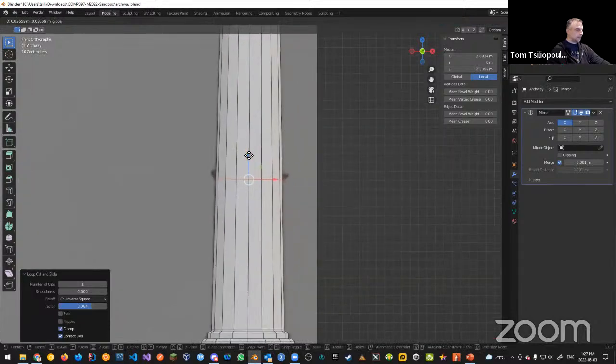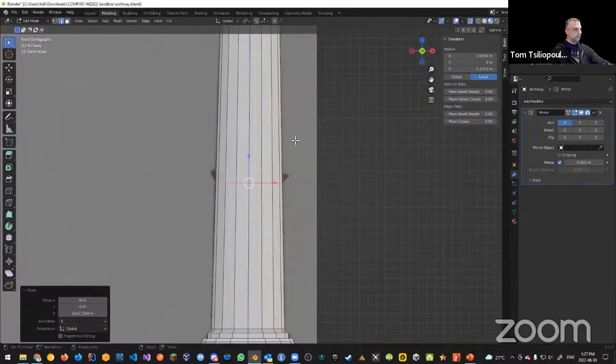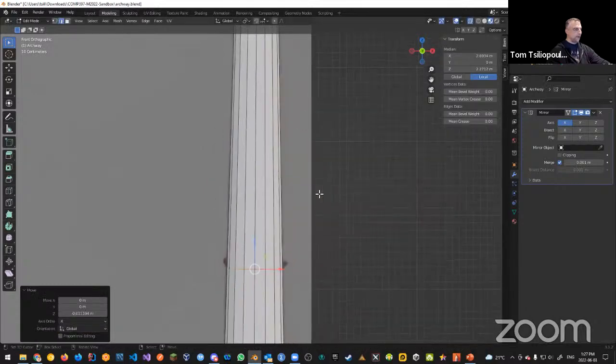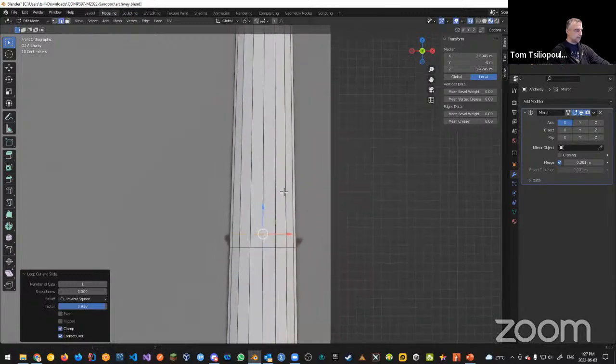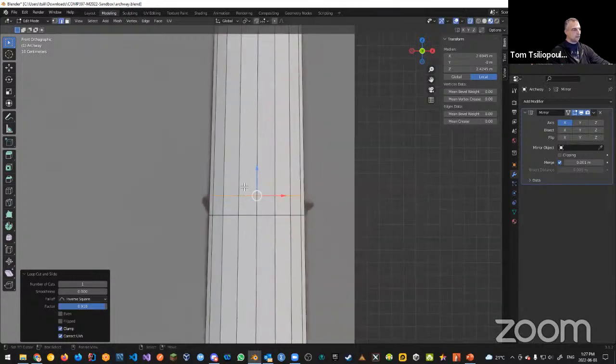And I can position it with the tool. And let me just zoom out. Let's do another one. So loop cut and slide up here, and then click it and bring it down so that it is right here. So again, this is what I'm thinking of where it's going to go, like right in here, approximately. And you can see that you can adjust these loops so that they're fairly good. I'm going to make my loop a little bit bigger.